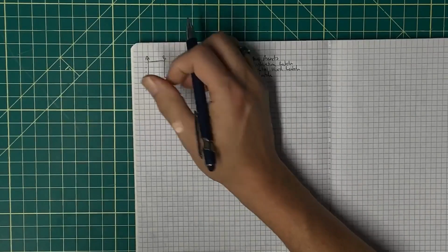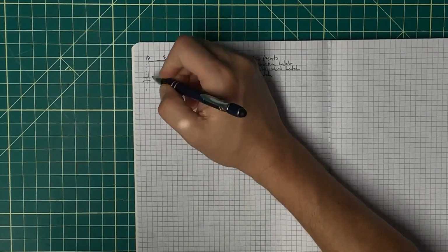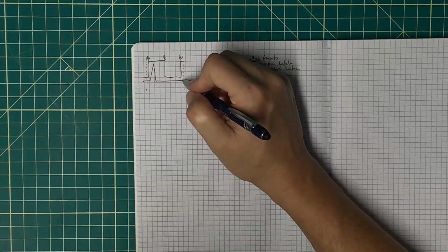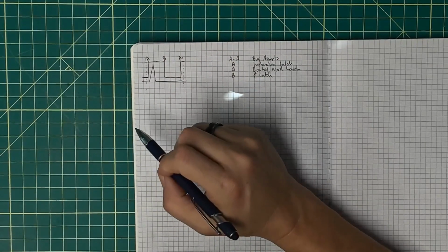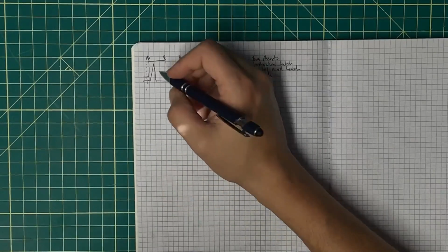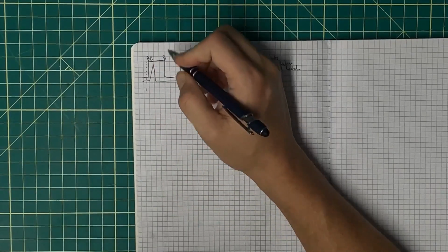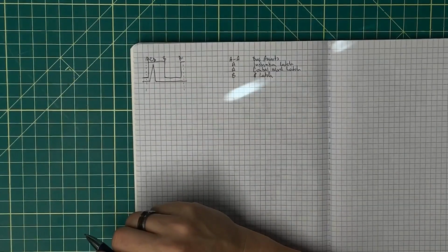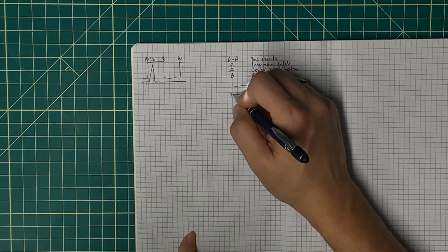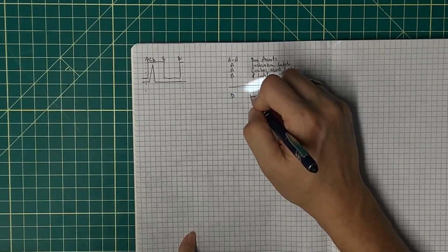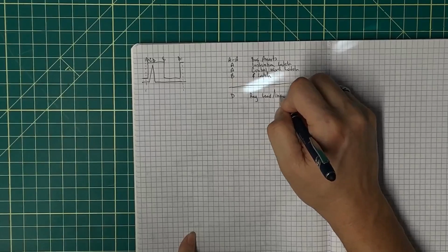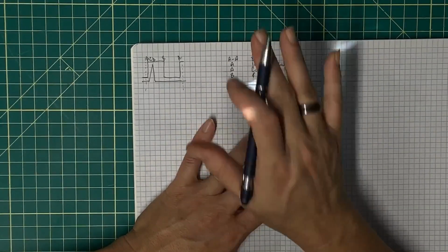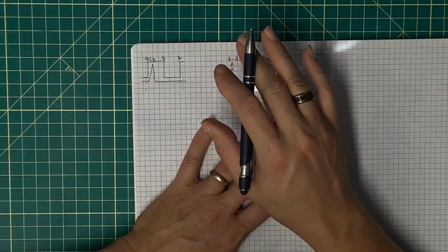And I ended up adding in there this signal, and I'm drawing it a little bit below, but it really is right over the top. It looks something like this. That was what I'm calling the spike clock, or spiked clock. And this rising edge here is transition C, and the falling edge back down here is transition D. So what I ended up doing is at D, I added my register load, increment, decrement signal. Now, again, I've shaped it differently. I'm not getting into the inversion and everything else that takes place.